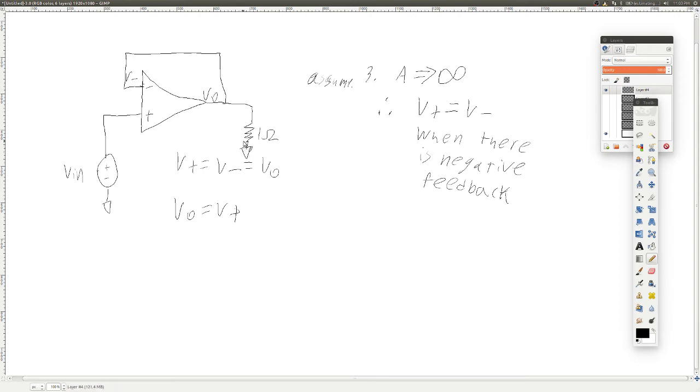Examples of small ohmage loads occur all the time in the wild. One example is a speaker. It's really hard to drive a speaker because they have a very, very small impedance. So we use circuits like this to make it possible to drive them. We add a buffer to go ahead and protect the signal from degrading as it's delivered to the load. So you'll never see a circuit this simple for driving a speaker usually. There's some other stuff that goes on, but that's the idea.